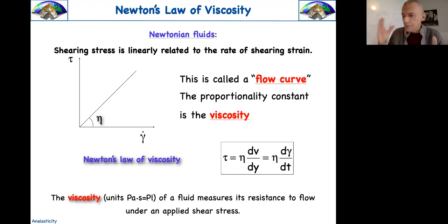So there is another extreme rheology, a simple one, but traditionally used in fluid dynamics: Newtonian fluids. Now you take here the shearing stress and not the strain, but the strain rate, and that's a line. So it's again a simple plot, like Hooke's plot, but instead of having stress and strain, we have stress and strain rate. So that's the dot there. And now this quantity here is keeping time inside it because its units are Pascal seconds or Poiseuille, as you want. That's viscosity, and that's an ideal but Newtonian fluid.